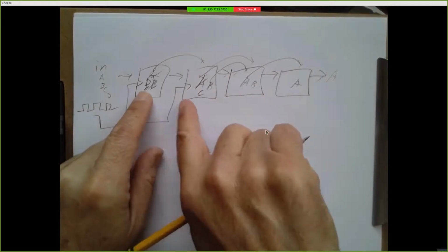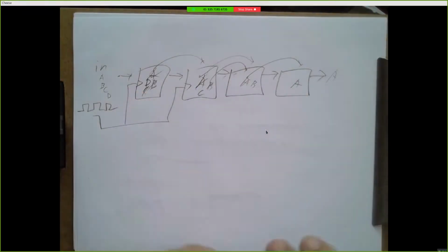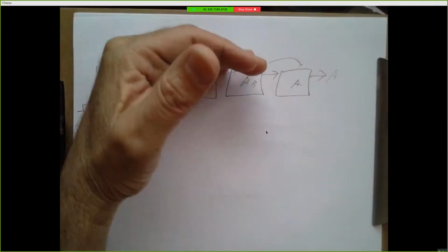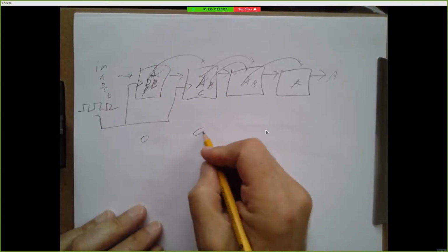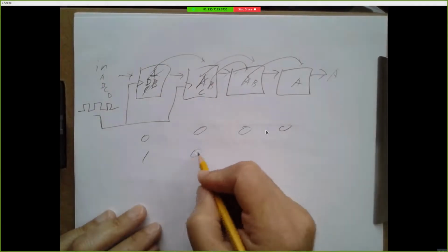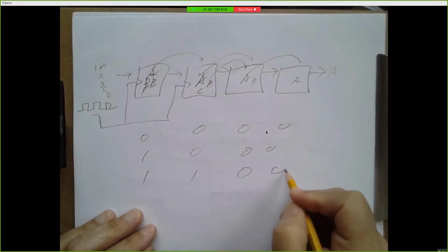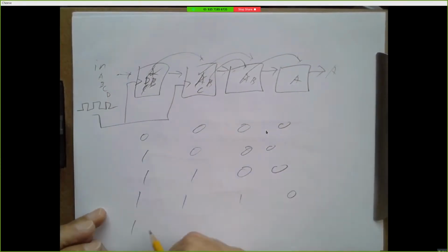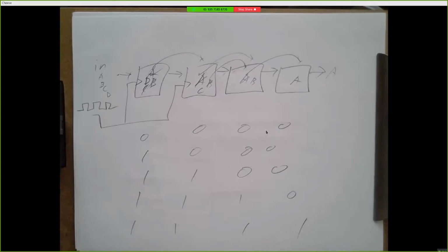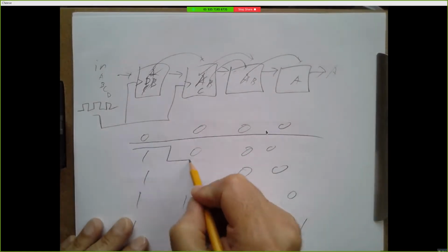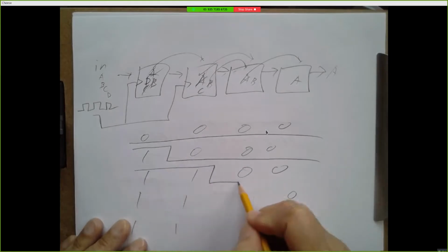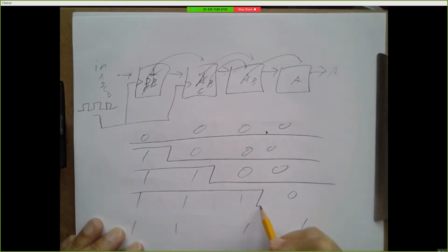And if you look at each of these outputs in a timing diagram, it's really obvious what's going on, because you'll see a nice staggered staircase. If you take your input and you raise it from a 0 to a 1, your flip-flop inputs will go from this to this to this to this to this. And if you plot this as a timing diagram, you'll see something to this effect.